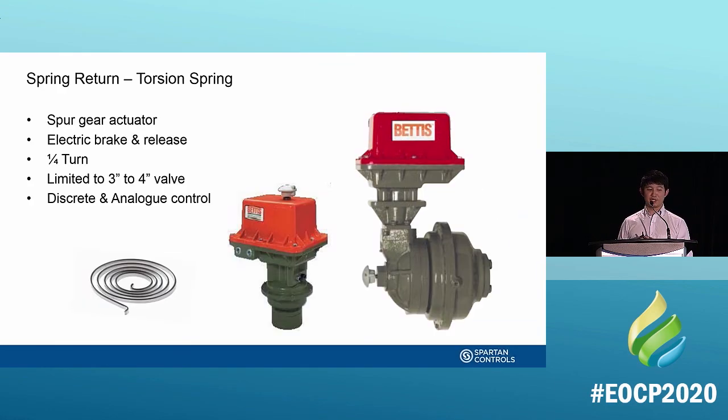Okay, I'm going to touch quickly on fail-safe electrics. Fail-safe electrics are extremely difficult to come by. It's not as simple as the pressure-loaded side. It's not so easy to just put a spring canister on that. So generally with fail-safe electrics, we'll need to use a spring case, but we'll connect that to the stem of the actuator. That's what you can see here in the slide.